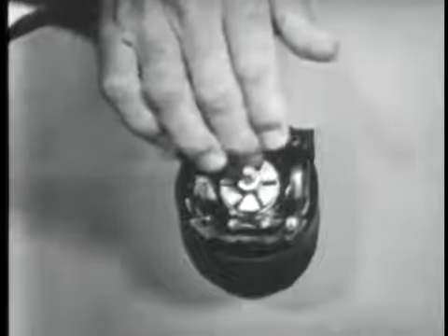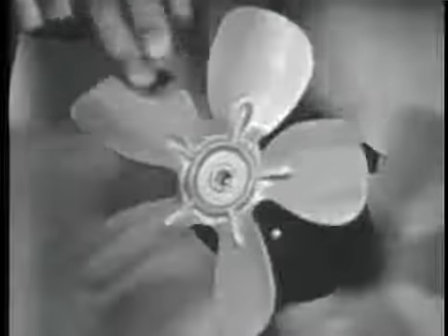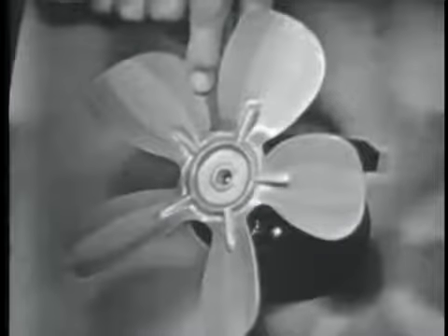Now, the external load refers to the job or the work that the rotor must do. That is, turn gears or operate pulleys, or maybe turn a fan blade. That you just happen to have with you. Happen to have one in my pocket, right? Very good. Now, when we put this fan blade on the rotor, we have increased the load or the drag on the motor. And therefore, it's going to turn a little slower. In fact, I've got to give her a little start there to get it going. Now, it turns slower. Now, before, the rotor was turning almost as fast as the magnetic field, under a no-load condition, of course. Right. Now it slows down a little.